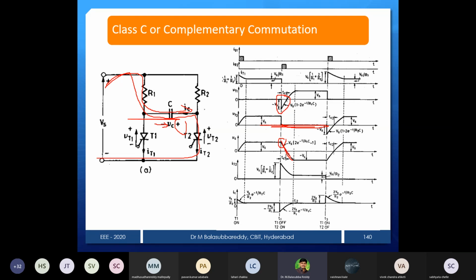So that means charge in the positive direction. With respect to the second plate, earlier it is positive, now it changes over to negative. Now because current is entering in this direction, earlier entering into this direction it is positive, now entering in the opposite direction it is negative. So now the changeover takes place after some time. You can say that at the T2 point, it changes over from plus Vs to minus Vs.